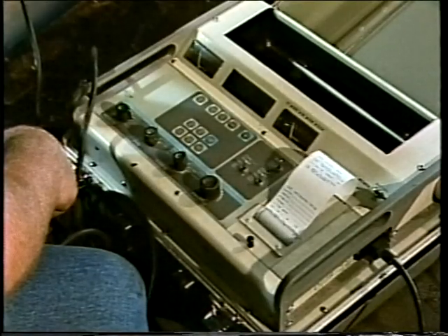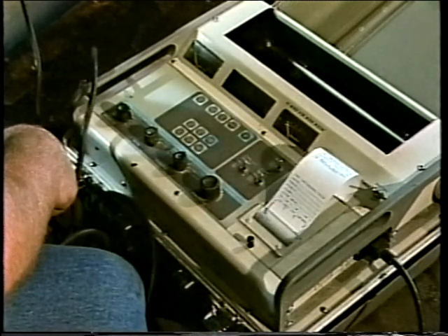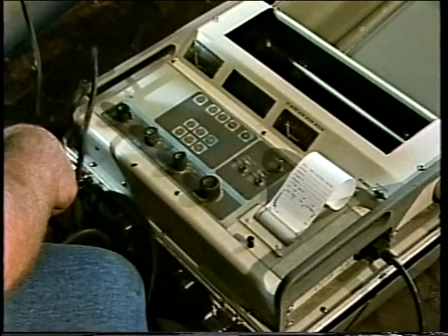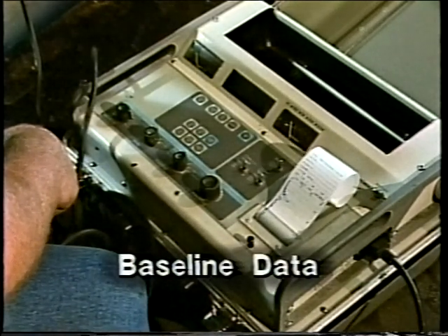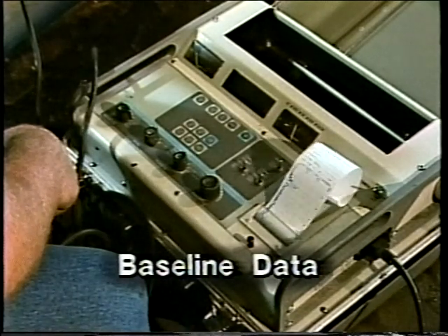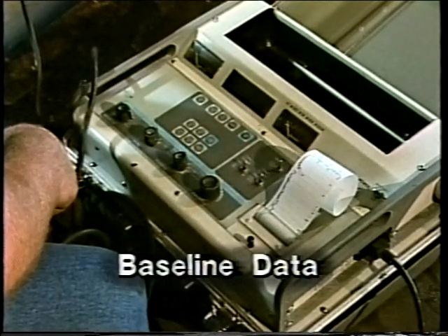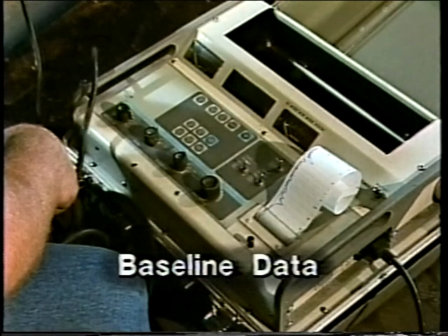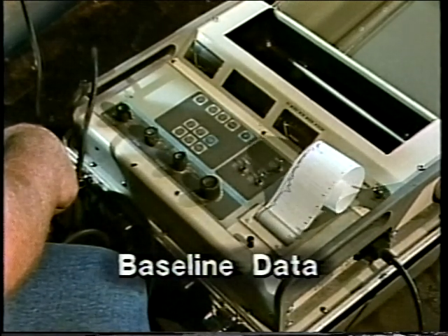When vibration data is collected from machinery, the condition of that machinery plays an important role in the accuracy of the readings. In this final segment, we'll concentrate on some of the basic guidelines that need to be considered before and during data collection. Perhaps the most important part of preparing for data collection centers around information known as baseline data. Baseline data describes both the initial information that is collected from new machinery as well as information collected to use for comparisons with future readings.